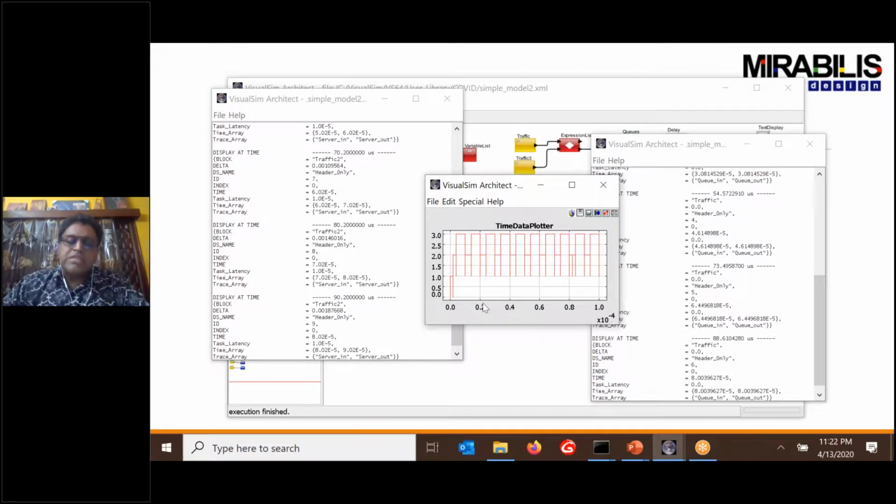So now what's happening is 1 came along, but it didn't actually finish because 2 came along. And before 2 finished, 3 came along. So 3 is continuously, when it comes in, 2 comes in, 2 comes in, but there's priority here, and as a result of which the queue is getting reordered to provide number 3 the highest priority, then 2, then 1. So now every time I did this, when I change the values, the tasks started behaving differently. Now I'm changing the priority, and the priority is also causing these things to move.